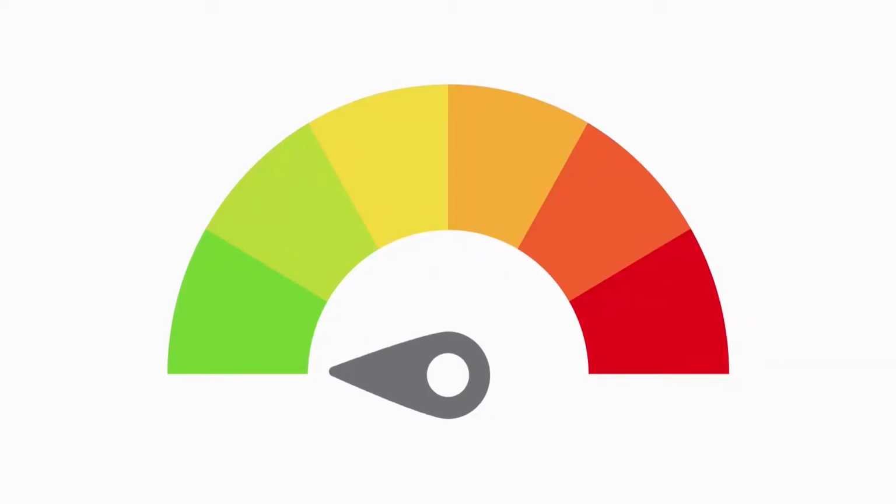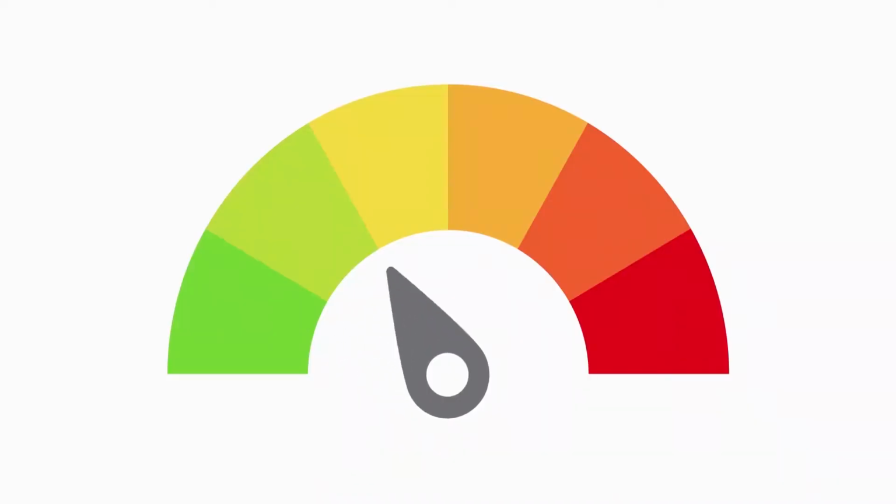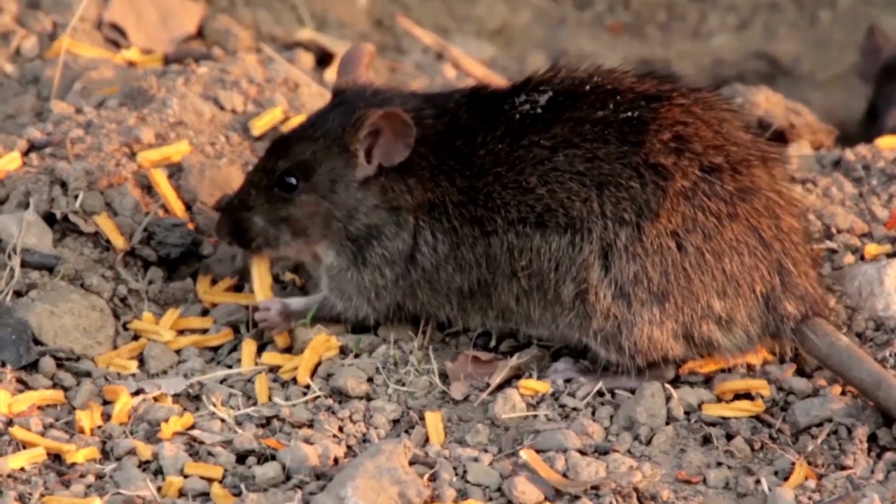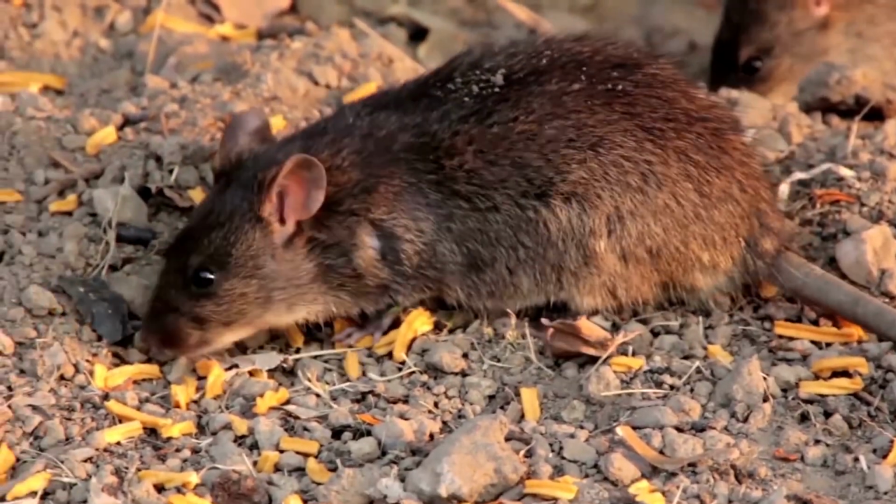2. Adjust the sensitivity dial to the correct position, and do not think that making it most sensitive will be the best option. The alarm system will be triggered by small pets and rodents if the sensor is too sensitive. Slight adjustments will be needed after installation to get the best results.